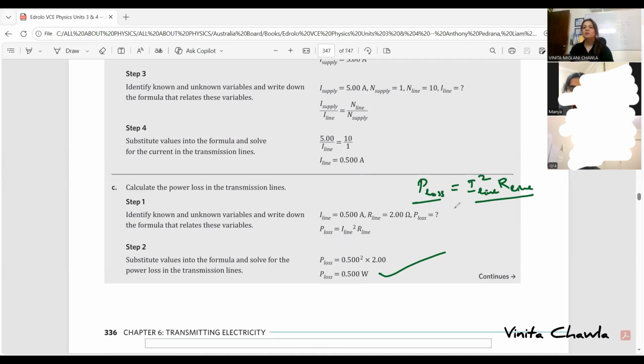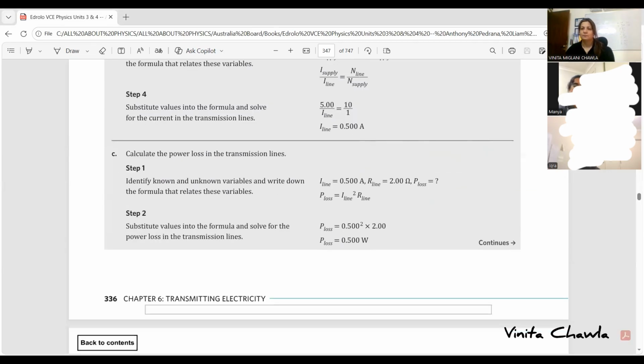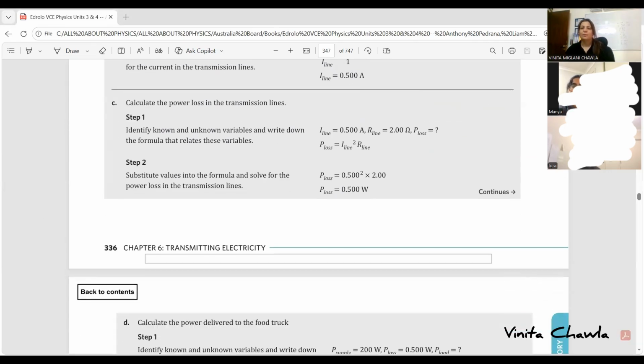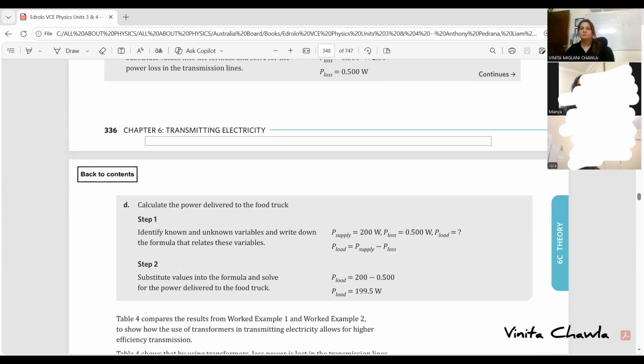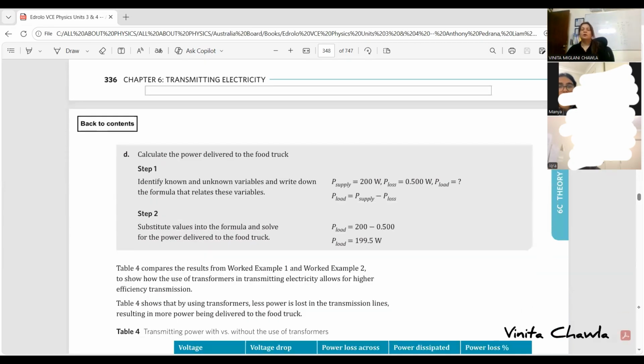Okay, so we need to understand the concept. Once the concept is clear, notations are clear, we can easily solve any question. अगर इसमें हमें करंट जो है वो आरएमएस वाला दिया होगा तो do we have to convert it or not? By default we assume the current to be in RMS. No, we don't convert. If they ask you to find peak current, only then you convert. If they ask you something like this, only then you convert. Otherwise, take the current as it is given to you.